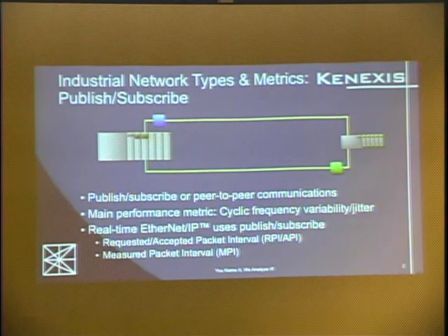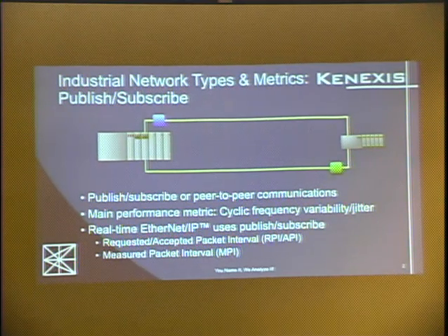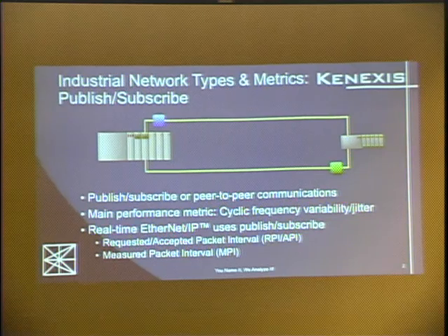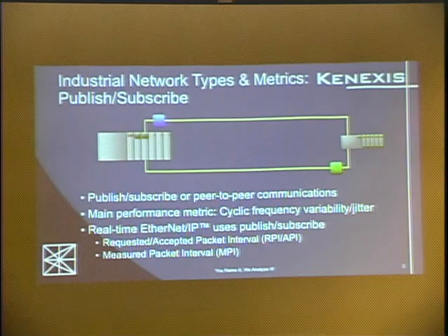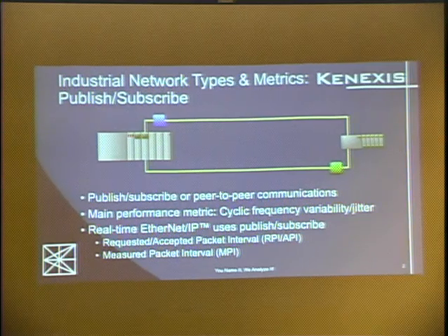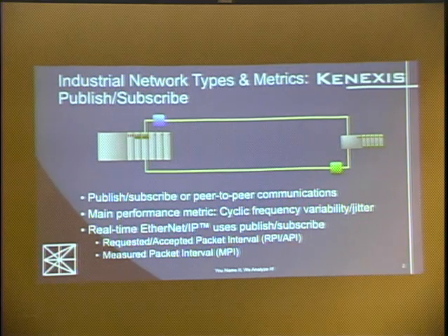For publish and subscribe, the big thing you're dealing with here is you don't care about the time it takes when the communication first starts up. You care about making sure that you get a packet from that device every 50 milliseconds or every 10 milliseconds. Some of them are down at like 100 microseconds or lower. So you've got to get that device that may have an 8 or 16-bit microprocessor to send you a packet on a very regular interval. Measuring that's pretty important to make sure your system stays stable.